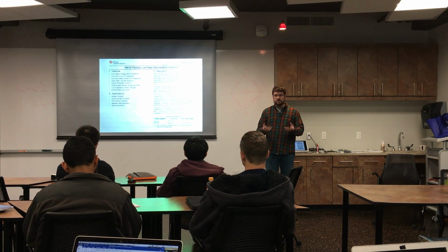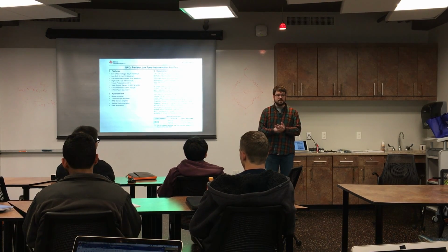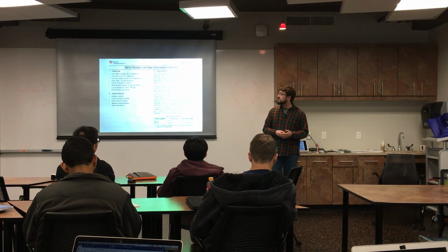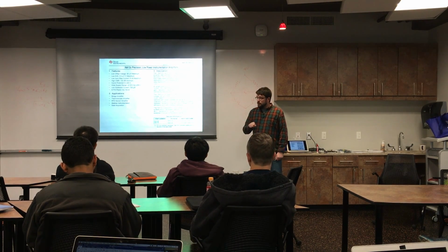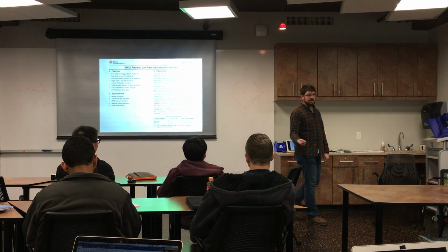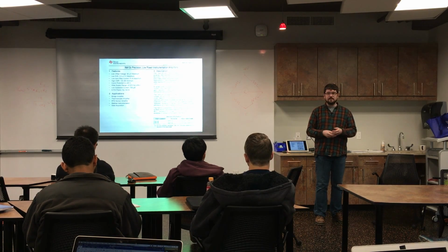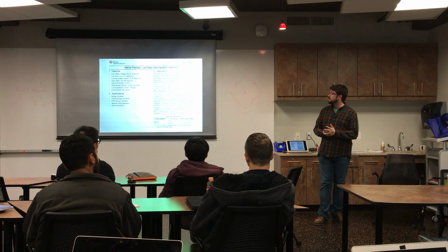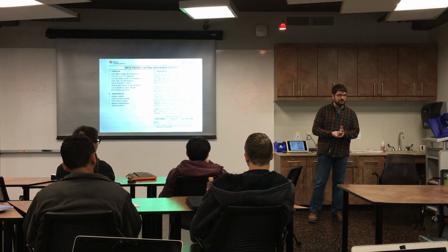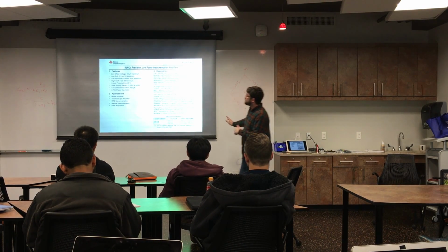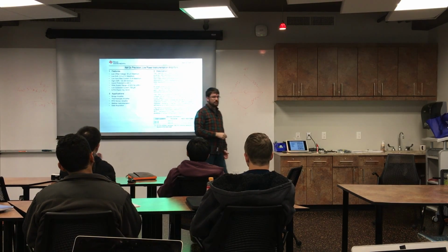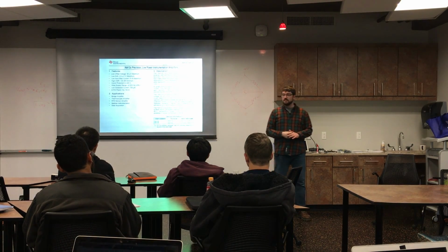A lot of the cheap, just kind of jelly bean op amps that you might get, the OP177 or the LM741, if you go much above the supply voltage, so say you're supplying it with 5 volts and you accidentally on the input put in 12 volts, it will release the magic smoke, and that will be the end of that chip. These are protected, so plus minus 40 volts on the inputs before you start having problems with these.